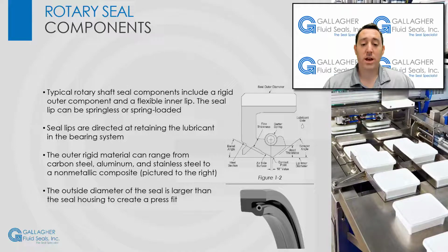The actual seal diameter will depend on the size and material of the seal, the size and material of the housing, and expected internal pressure and temperature. PTFE rotary seals can be designed without a metal can, and instead have a groove machined into the outer diameter of the seal. An O-ring will be inserted into this groove.